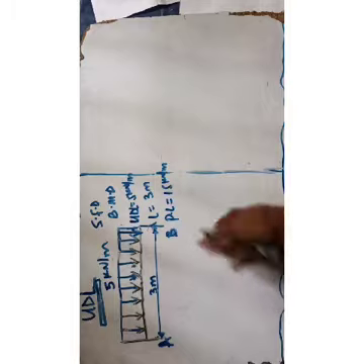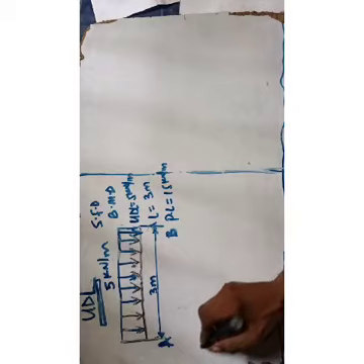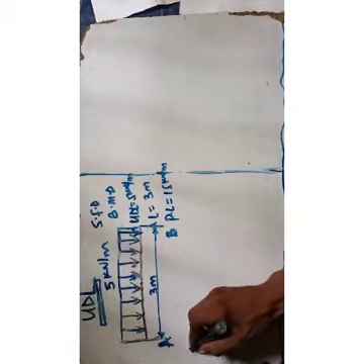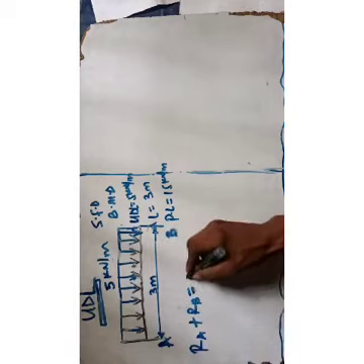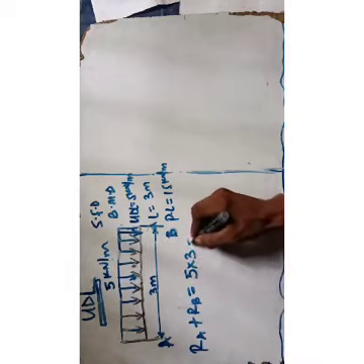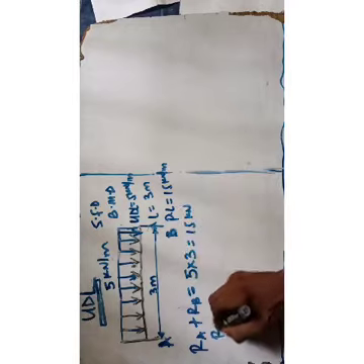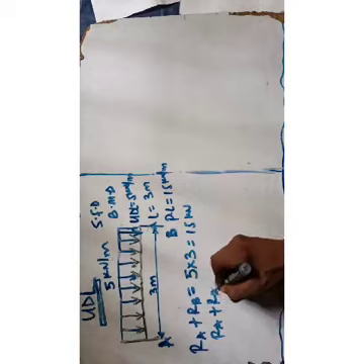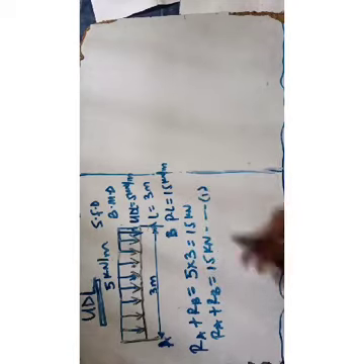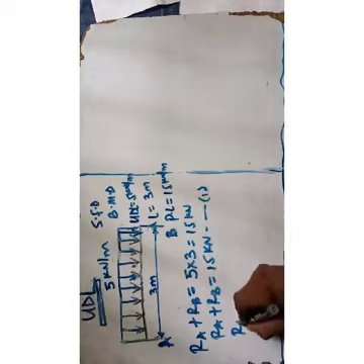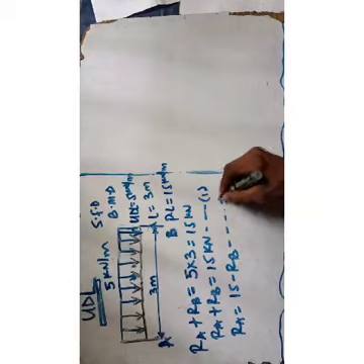So the next thing you do, you understand that you convert to area. Okay, now you draw a diagram again. From the equation you have Ra plus Rb equals what? That is 5 times 3, and that will be 15 kilonewton. So you can have it as Ra plus Rb equals 15 kilonewton. That is equation 1. Next thing you do is you write Ra equals 15 minus Rb, equation 2.